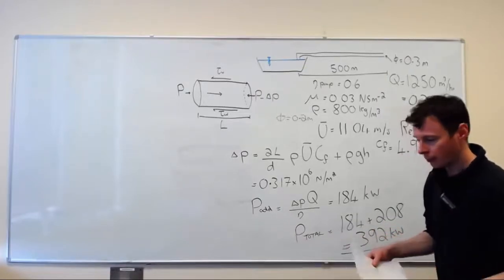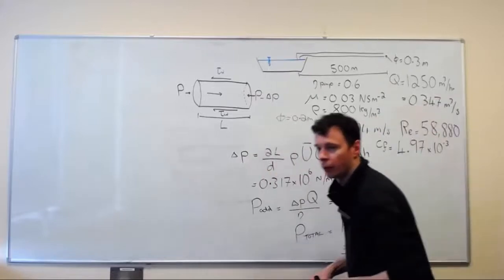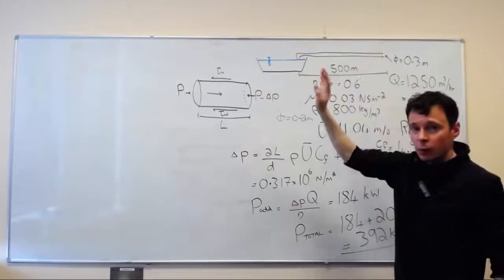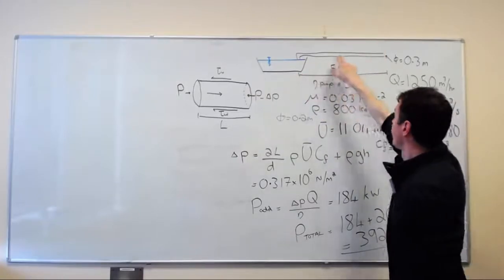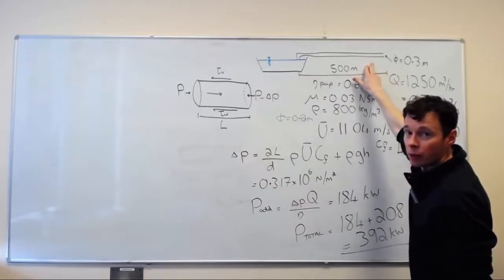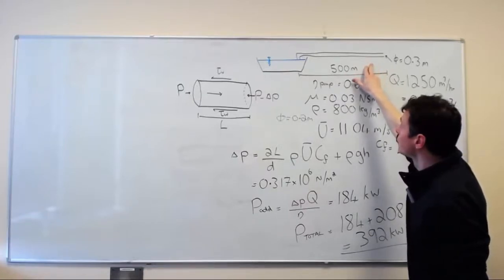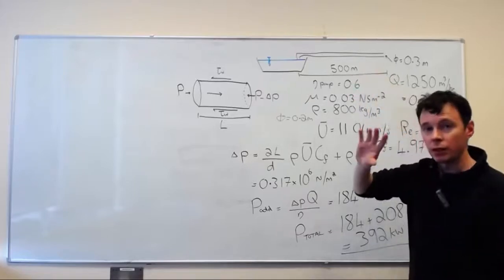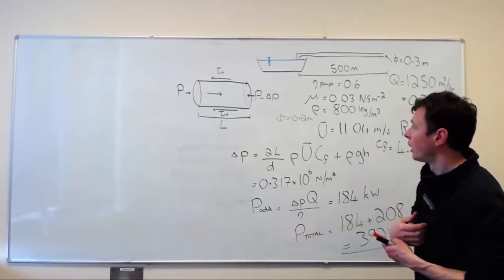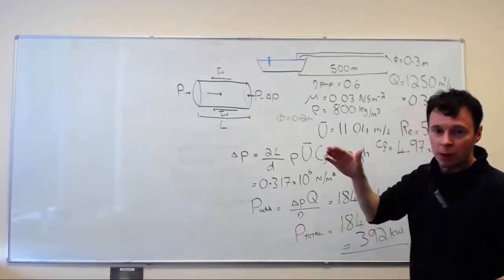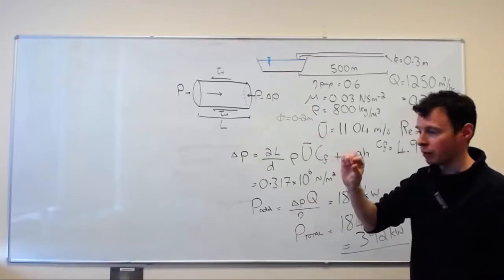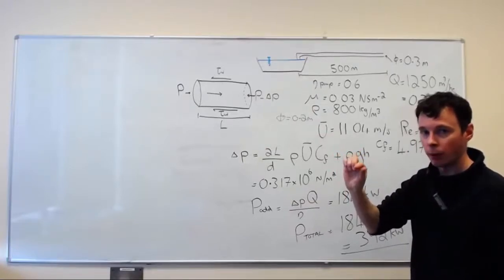And you've seen now the issues with viscous flow and overcoming friction. And you've done the Moody diagram in your lectures, so you've had a look at that. Obviously, when you've got very long lengths of pipe, you need a large diameter pipe. That reduces friction because for a given roughness length, it will reduce your relative roughness. So if you have a roughness height of 1 millimetre, that's far less of a problem if your pipe is 2 metres in diameter. If it's 5 millimetres in diameter and your roughness height is 1 millimetre, you're in trouble.